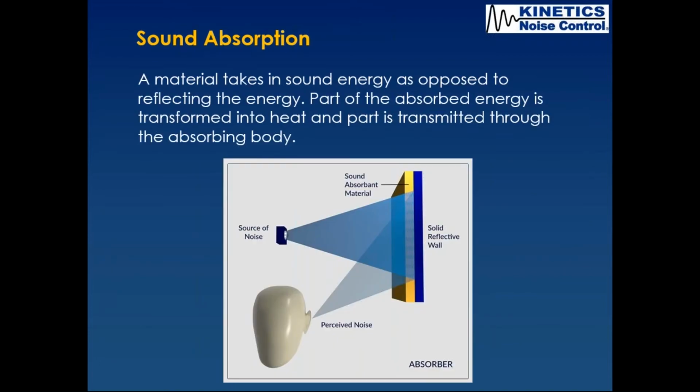And sound absorption is strictly this. Sound is energy. You have a sound source here that's giving off sound power. And then once it moves away from this sound source and enters into the space, it becomes sound pressure. And that is energy, right? So we look at the blue surface here. It's a very hard reflective surface. And what we've done is we've mounted a sound absorption material to that surface.